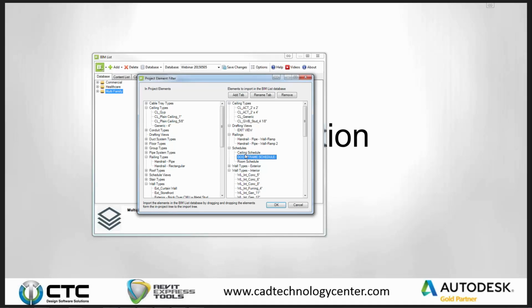In the case of views that already exist, what I would probably want to do is rename the old view and drag in the new view and leverage that as reassociate some of my references to that view and whatnot if there was something major that I needed to update. Or I could go through the traditional old process of opening up the two side by side, grabbing the actual graphics in the one and copying across the actual drafting lines. But if I was trying to drag exit view in a second time into my project, if it was already there, it would basically go in there and go through the process of making a new view that's a duplicate with like parenthesis 1 or 2 after it.